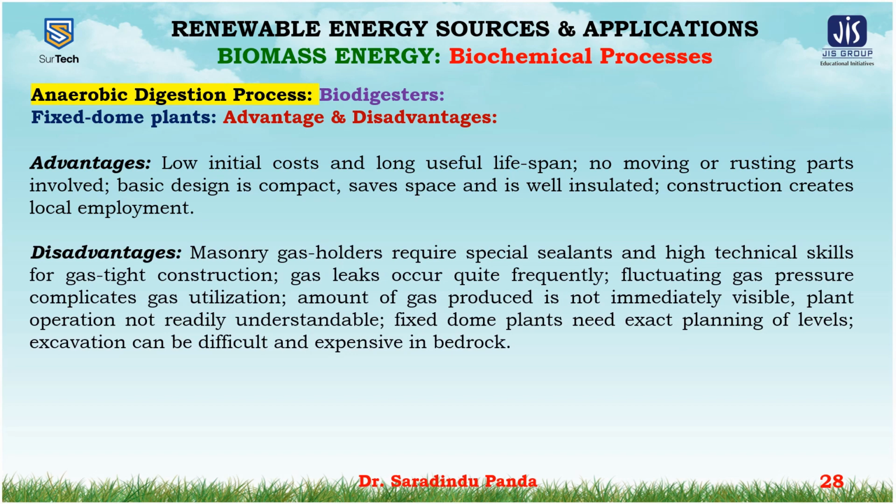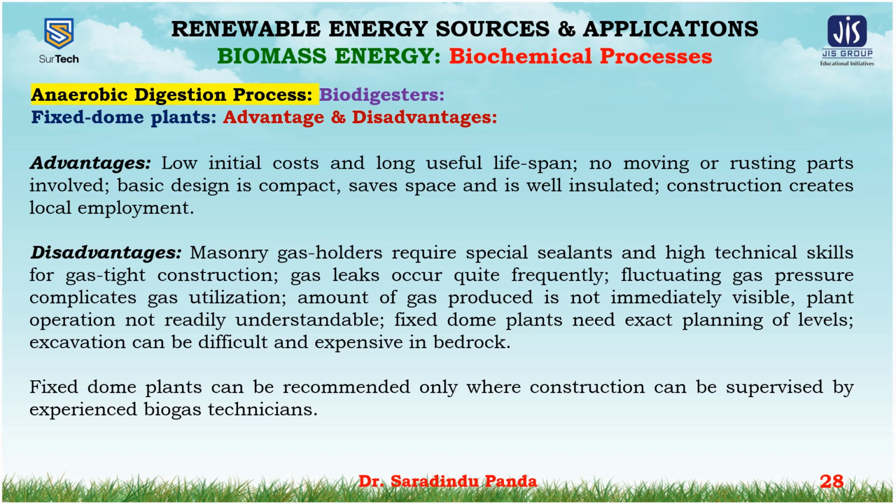Disadvantages: the masonry gas holders require special sealant and gas technical skills for the gas-tight construction. Gas leaks occur quite frequently. Fluctuating gas pressure complicates the gas utilization. The amount of gas produced is not immediately visible. Plant operation is not readily understandable. Fixed dome plants need exact planning of the levels. Excavation can be difficult and expensive in bedrock. The fixed dome plants can be recommended only where the construction can be supervised by experienced biogas technicians.